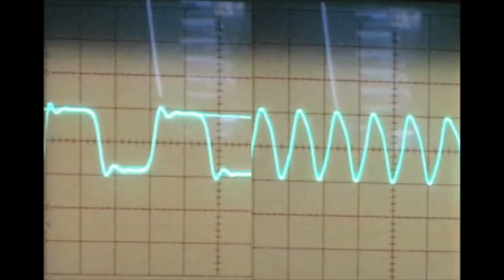And that's to be expected because, like I said, we're shaving off the upper harmonics. But if you notice the difference between the 20 megahertz wave and the 60 megahertz wave, there's no difference in the actual amplitude, meaning that we are not cutting down in our analog bandwidth into, or past, I should say, the fundamental of the frequency, i.e. our bandwidth is over 60 megahertz.